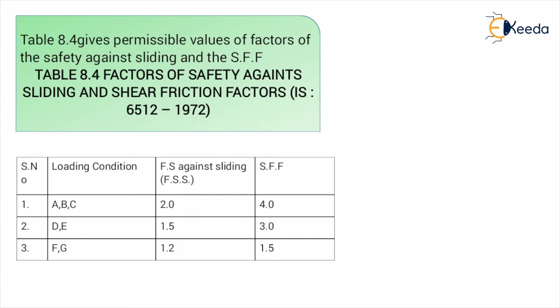So there is water pressure on the upstream side and tailwater on the downstream side. Through the cracks and pores, the water will percolate into the base or foundation of the dam, and this water will exert pressure. This is called uplift pressure. So water pressure on the upstream side, tailwater pressure on the downstream side, and uplift pressure.